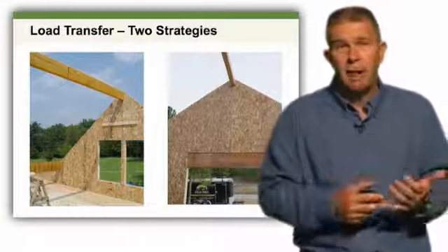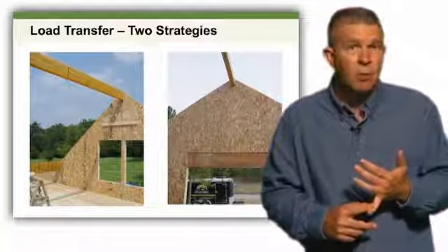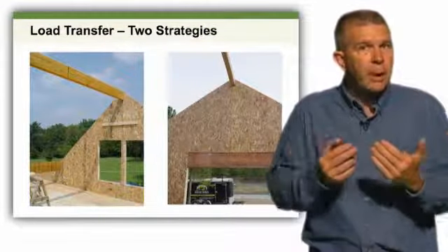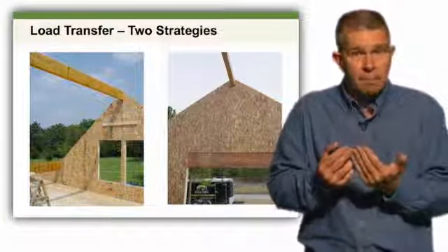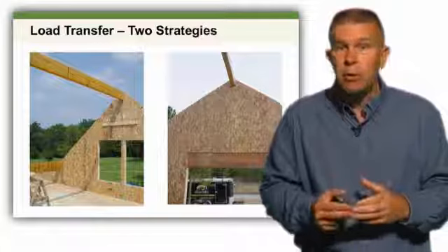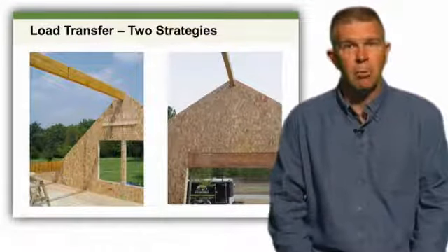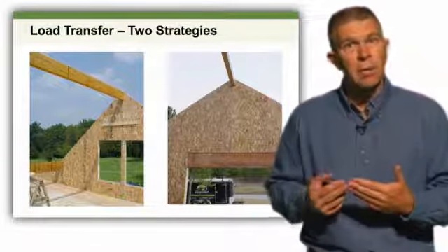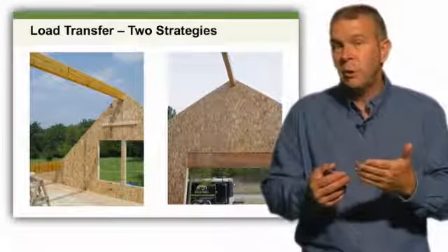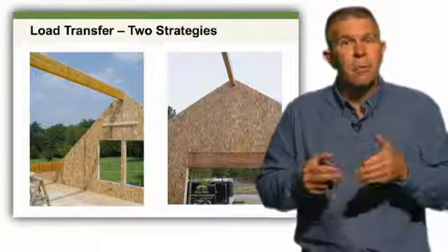The picture on your left, obviously we have a large ridge beam. That ridge beam comes into the top of the gable wall, and where those gable panels come together at that point, we are carrying through posting all the way down through those two windows down into the floor system or the foundation below. If we look at the picture on the right, we're dealing with a very similar situation in that we have a ridge beam and we're posting down through, but we're hitting that header.